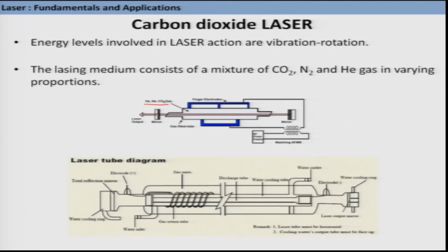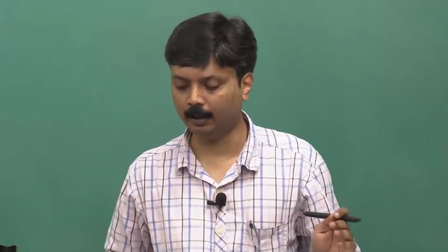And this is another design I have shown here. The reason is that this laser also needs to be cooled down. So it is cooled down by supplying water. This water goes in through this inlet, and then goes out from this outlet, correct? And there is a sheath of water all around, and it continuously cools down this whole system comprising the electric discharge and this gas cylinder. This is required like in the other solid state lasers that we discussed earlier.